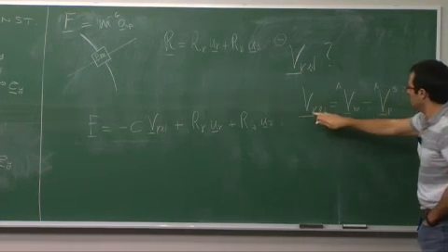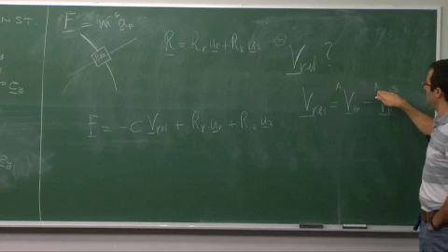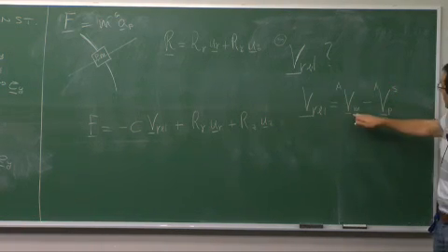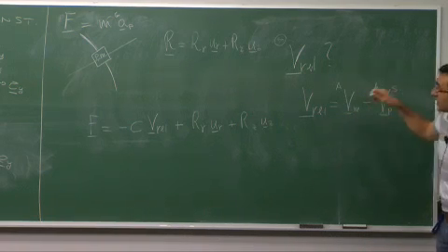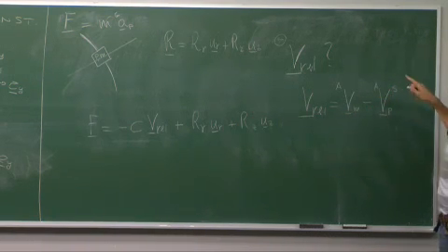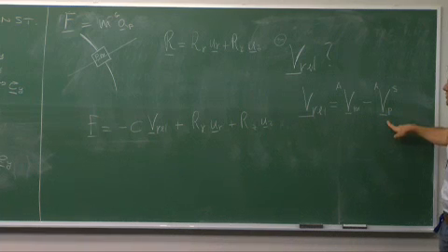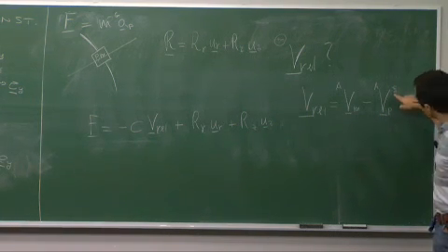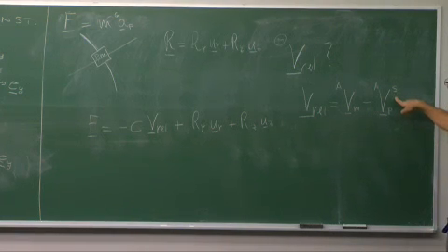And we demonstrated that this is frame independent, so this can be A, G, B, whatever. It doesn't matter. So it's the difference between the velocity of the actual particle of mass m and the velocity at the point of contact of the particle P as seen belonging to the surface S in that same reference frame.